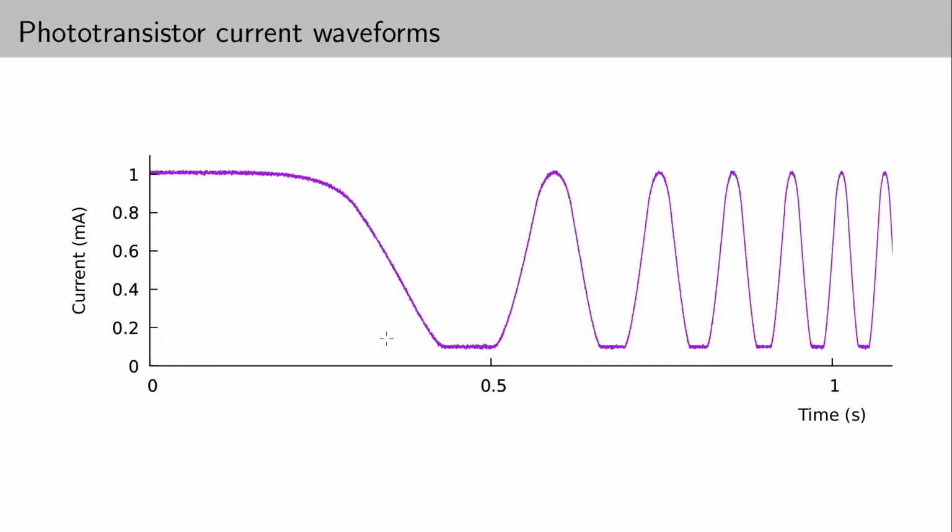And I've seen quite a lot of examples with LTSpice where people do clever things with pulses and switches to generate arbitrary or semi-arbitrary waveforms. But this approach using PWL files means you can do quite sophisticated simulation outside of LTSpice and then import the data and use it to drive your simulations. So that's what we're going to do now.